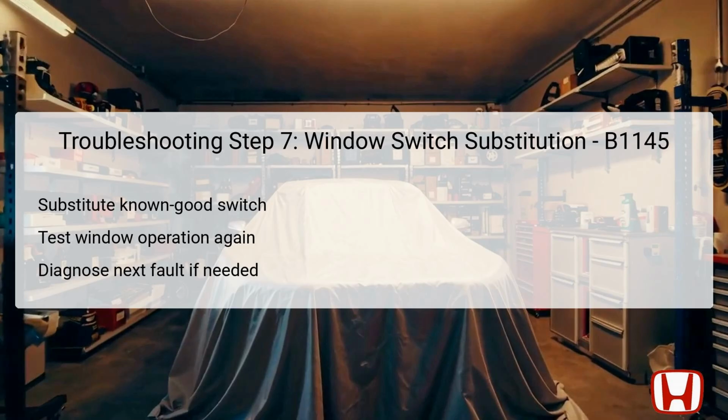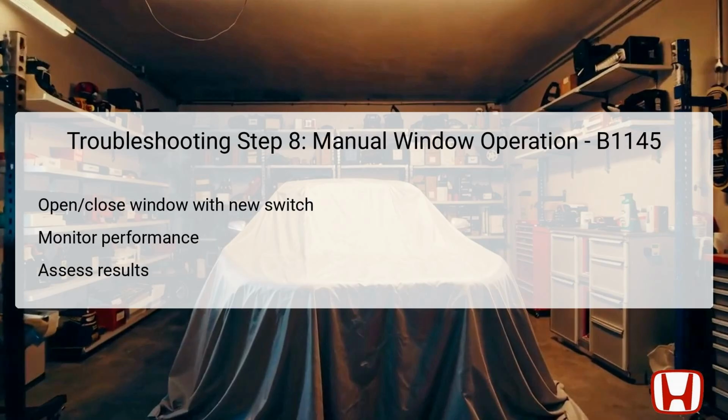If the window operates correctly afterward, this indicates that the original switch was faulty, leading to the need for replacement. Should the issue persist, the technician must then investigate other components, such as the power window motor. Next, after substituting the switch, the technician should open and close the front passenger's power window using the new switch.